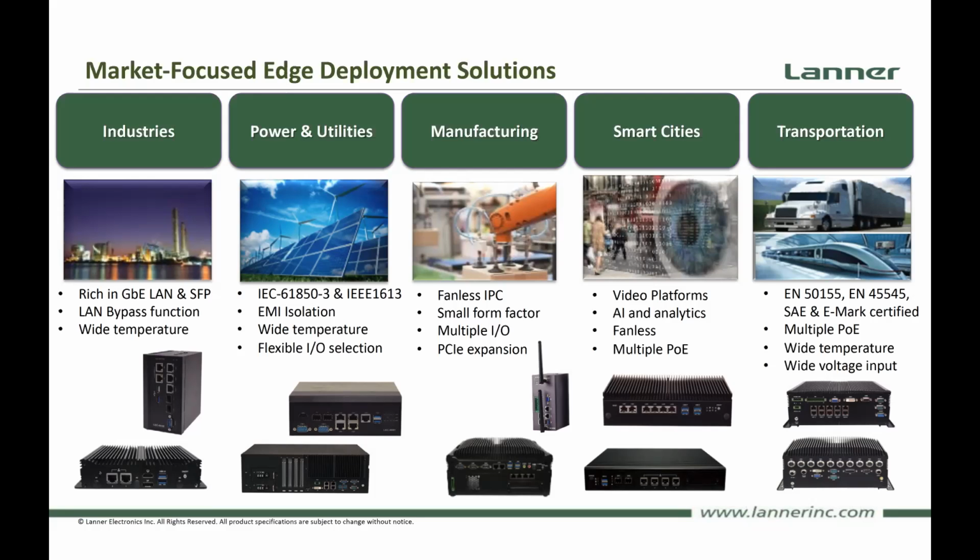You see IEC-based substation automation, workload consolidation and virtualization, also using custom-built hardware with the software to do electrical equipment monitoring and advanced predictive maintenance. Another example is in water and wastewater, using again Modbus communication to gather vibration analysis data for tank farms, for example, to have continuous monitoring of the structural integrity of the tanks.